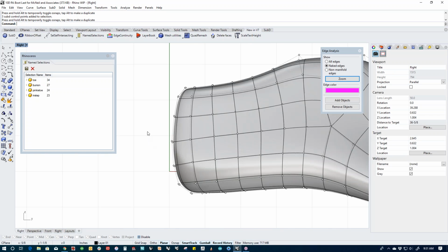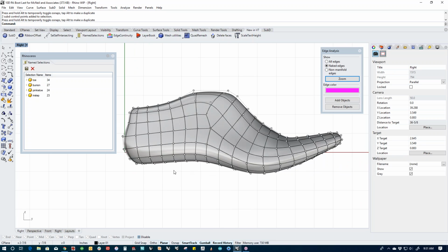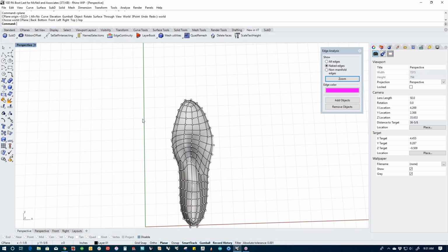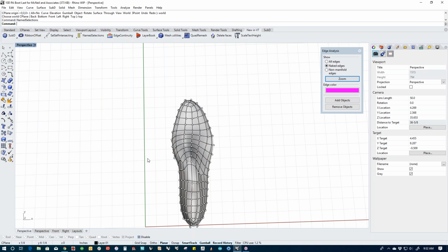The thing about SubDs, and let's say they've got a weird heel shape, I can even pull this out to make a perfect heel cup so that it doesn't pull their socks down when they walk. I can do the arch, the instep, anything else, okay? So now I've got a completely custom last that fits my customer's foot. And that's great. And at any time, I can go back in and edit any of these things because these selection points are saved, okay?